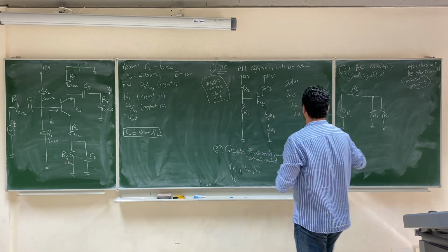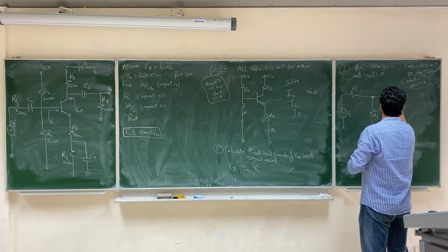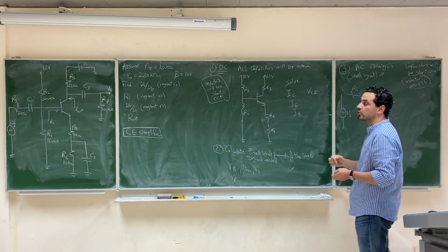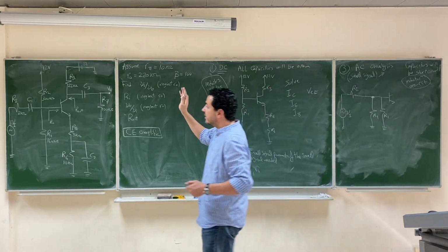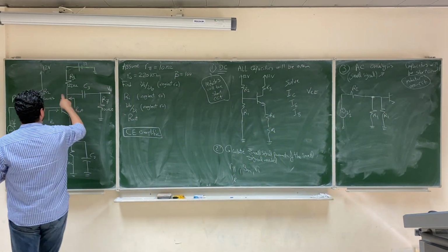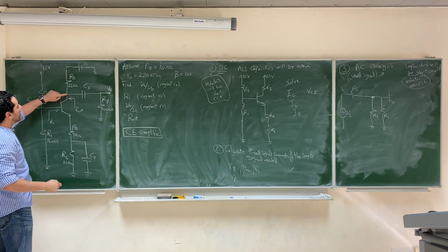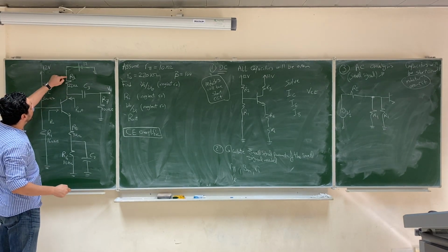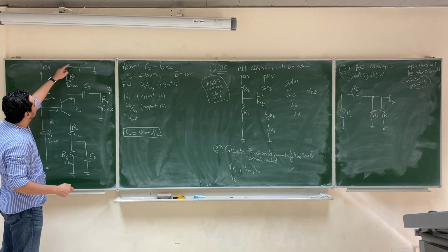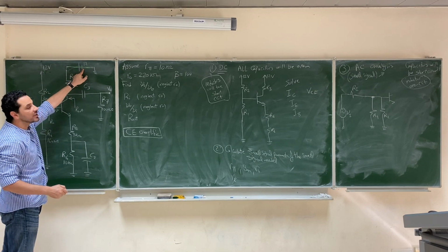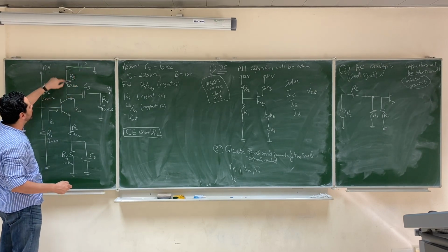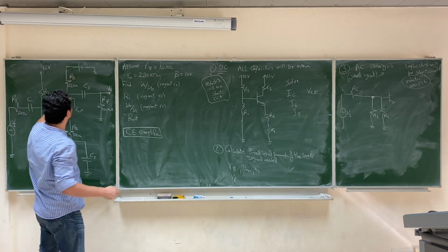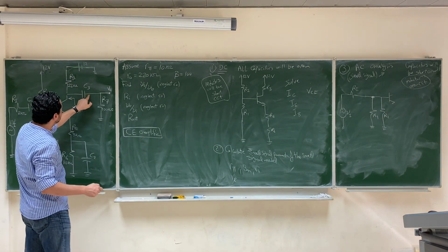And then the transistor comes. So I'm going step by step, as you see, and this is what you should do, step by step. For the transistor, we have the emitter, we have the collector. The collector will have this resistance R3 connected between the collector and the ground. Why the ground? Because we deactivated the source. So we have R3 between the collector and the ground. And then we have a short circuit.